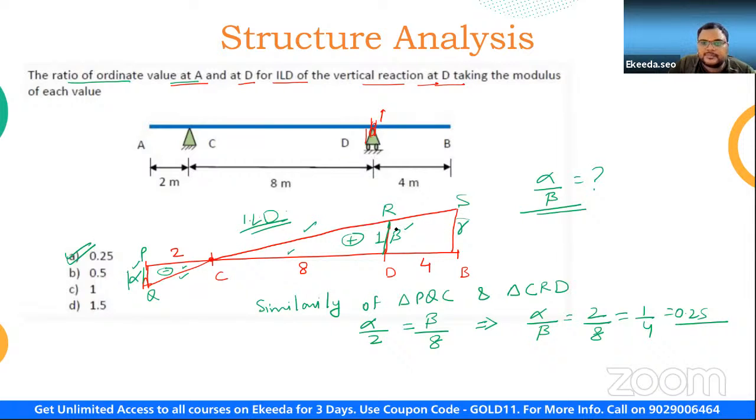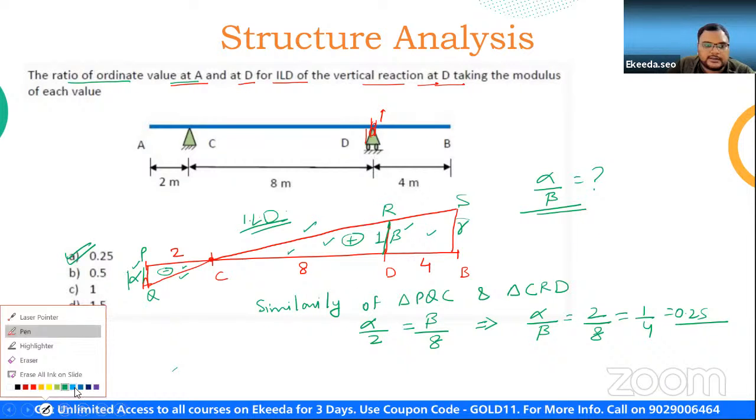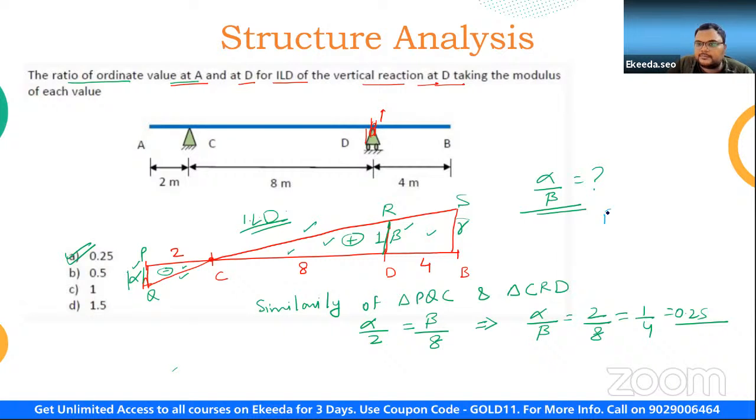Can anybody tell me where this ordinate value is maximum? If you look at this diagram, you can simply say this is 1 and this is going to be bigger than this one. So if you have to find gamma, I can use the principle of similarity of triangles in these two triangles, right? Let us say beta by 8 is going to be equal to gamma by 12, right? So this gamma is going to be 3 by 2 times beta, right guys?